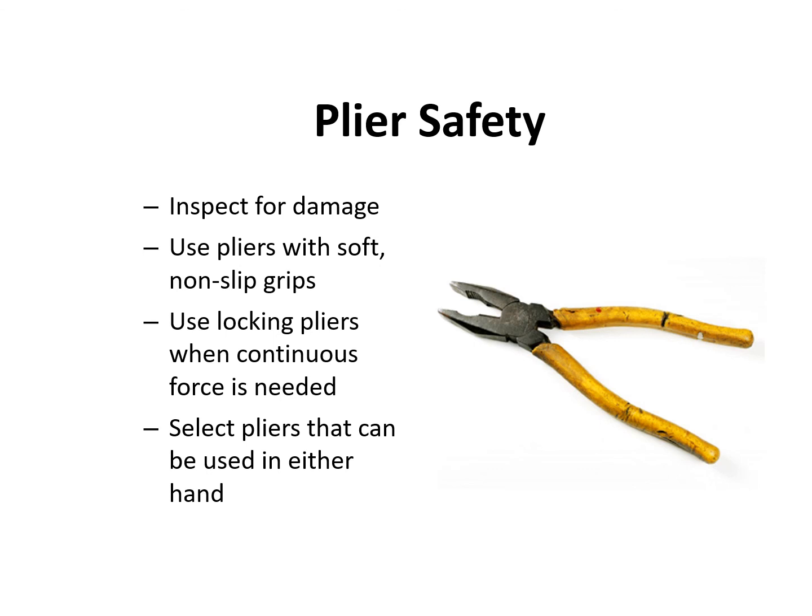When using pliers, inspect the pliers for any signs of damage. Use pliers that have soft, non-slip grip handles. Use locking pliers if continuous force is needed to hold firmly to an object for a period of time. Select pliers that can be used in either hand.